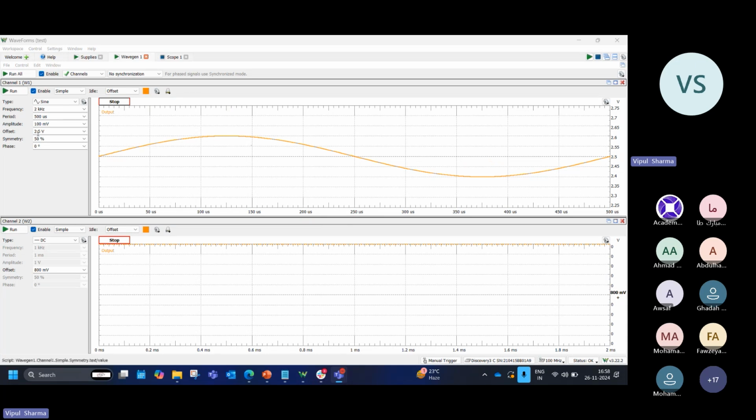That input signal will lie. So that DC voltage is defined using this. That is 2.5 volt I have used as DC voltage. You can select any other voltage if you want. Since this is a 0 to 5 volt op amp, I have used a center, middle DC voltage as an offset here.